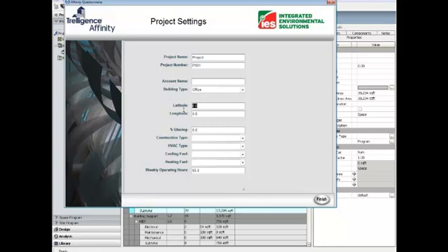The latitude and longitude of the site will be used to gather weather data and run climate analyses. I'm entering the latitude and longitude for a site near the Chicago O'Hare Airport. I'll enter 35% for the glazing, which can be changed later after we run the analyses. And for now, I can select the brick or block wall as the construction type. For the HVAC type, I'll choose the fan coil system.